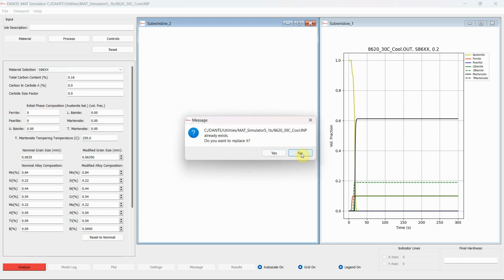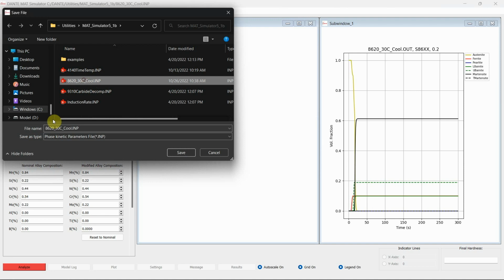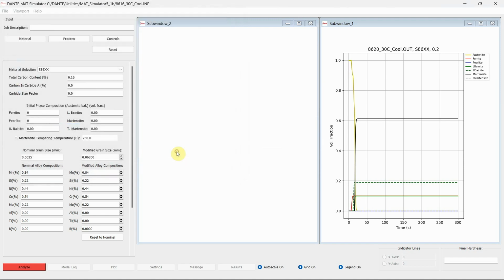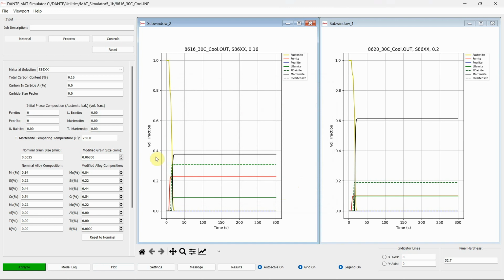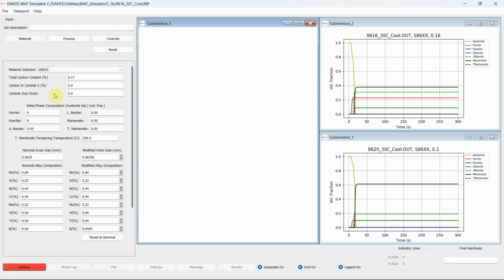You then wonder, on the new cert you saw a low side carbon of 18. You're wondering if 16 carbon is low enough to drop the core hardness out of spec. MatSim with 16 carbon predicts that the hardness would drop below 33, matching up with your worst case situation. You want to know what carbon hits the bottom of the spec, so you rerun it at 17 carbon and you're right at the bottom. You're now closing in on the problem.